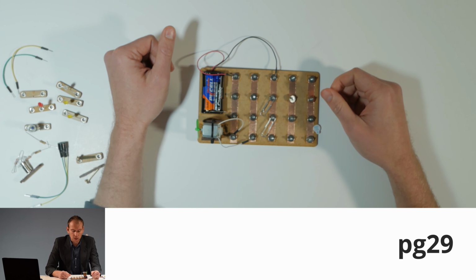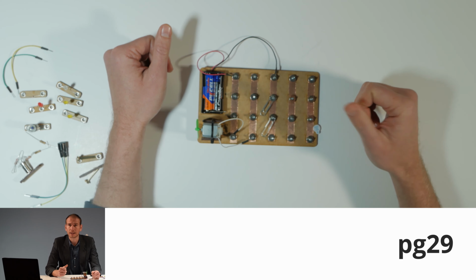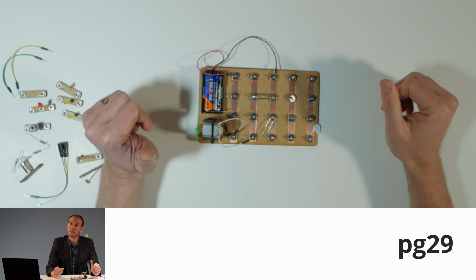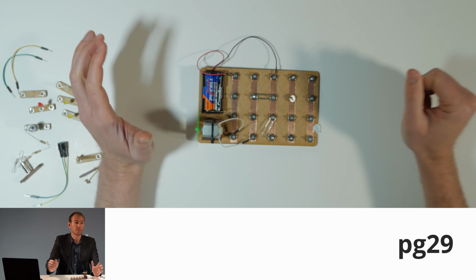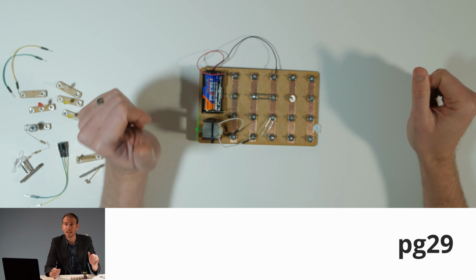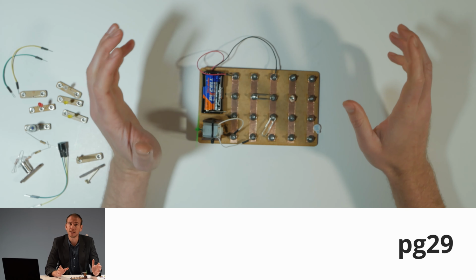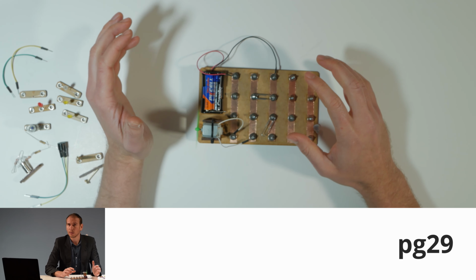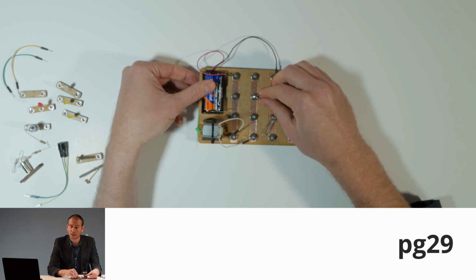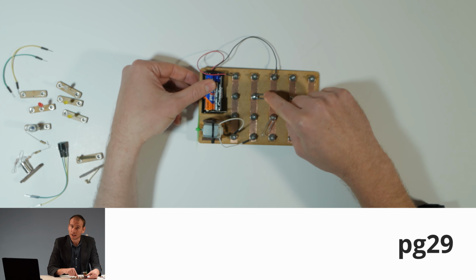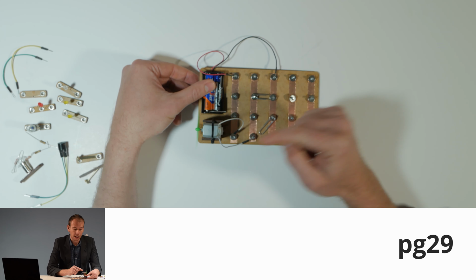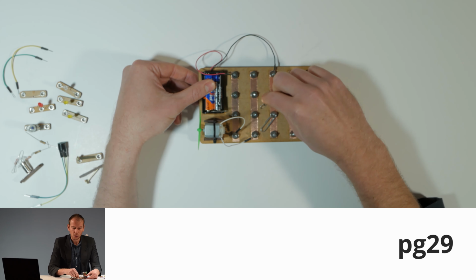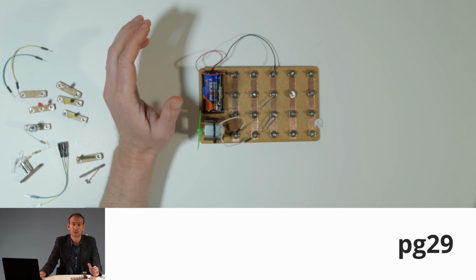So let's say I walk into the workshop and now I switch on the plug at the wall and suddenly the grinder comes on. That could be very dangerous because it could be lying next to a computer, or next to somebody's hand and it suddenly cuts their hand. So that's a very dangerous thing. So we are definitely not going to do this option. What is this option called? This option is the OR function. Either switch 1 or switch 2 needs to be on and the motor will turn. So this is ideally not what we want to use. The OR function is not going to work for this specific case.